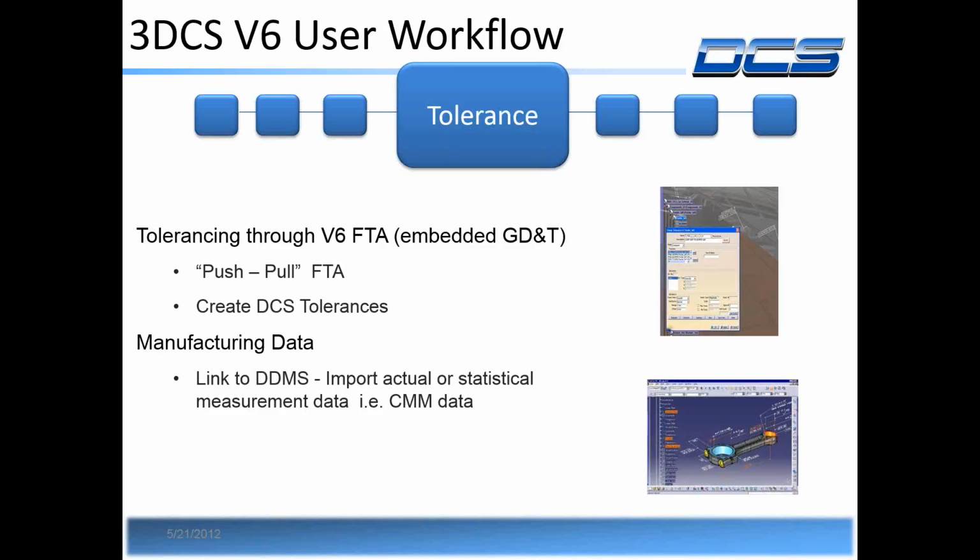Hopefully they're design changes, process changes. They might be tolerance changes we might have to reduce, but hopefully we can increase tolerances. Maybe we have our tolerances too tight. We push them back to ease up the burden on manufacturing. And that's because, of course, a larger tolerance is easier to make. That's right, and theoretically should cost us less. Maybe we would scrap fewer parts because some tolerance was too tight for some reason. So definitely that's going to be an advantage to the guys doing the manufacturing. Gives them some options on how they manufacture that part.